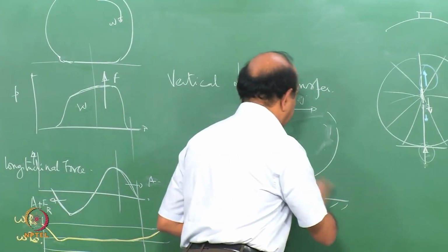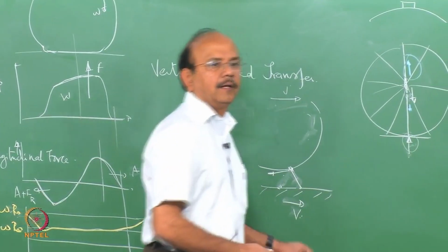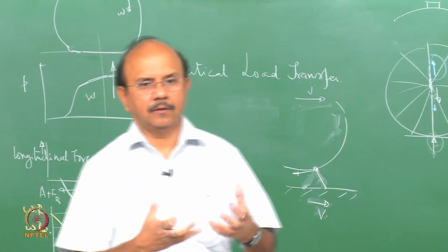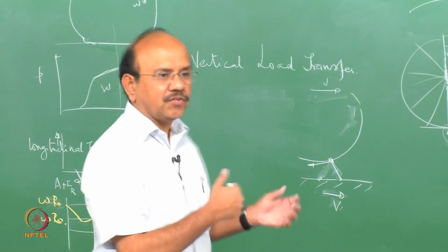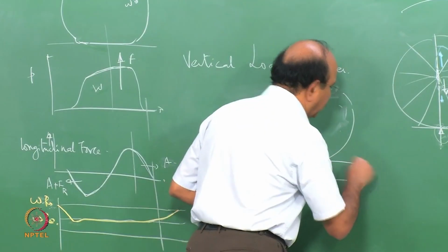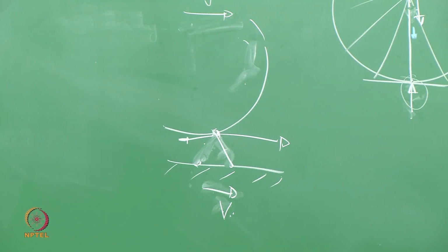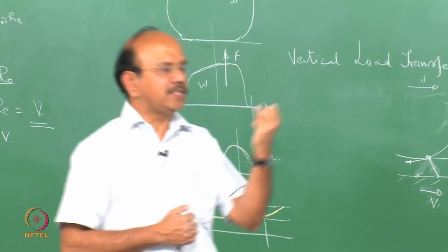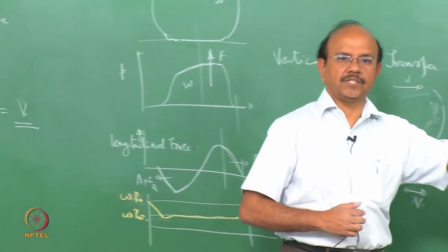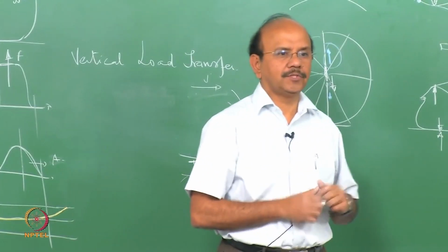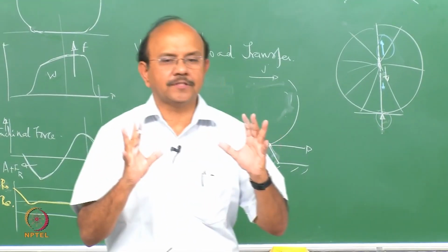With the result that there will be a stretching of the tread, and that stretching would give the force which is the traction force, right? So stretching in one direction gives the braking force, and stretching in the other direction gives the traction force. So it is this stretching, however you view it, that is responsible for all the forces that are developed on the tire.